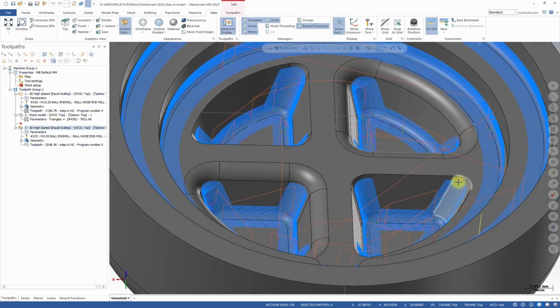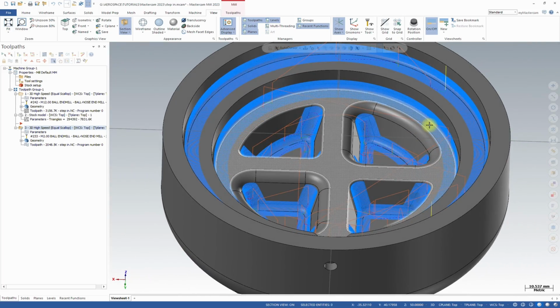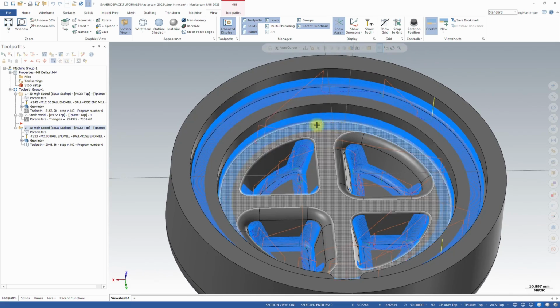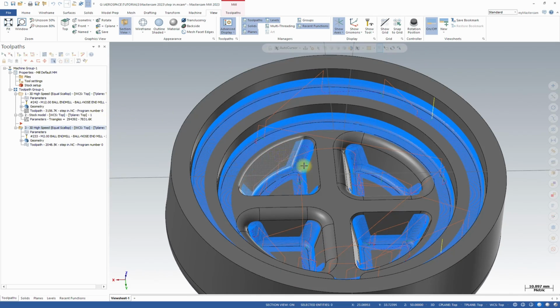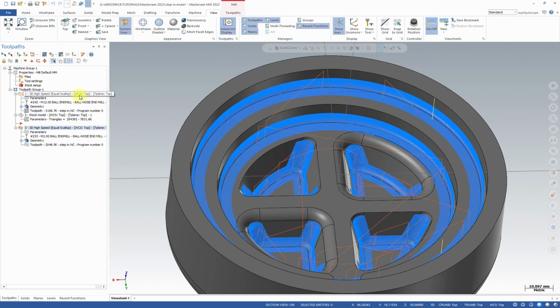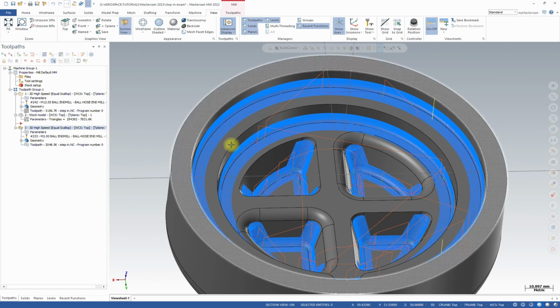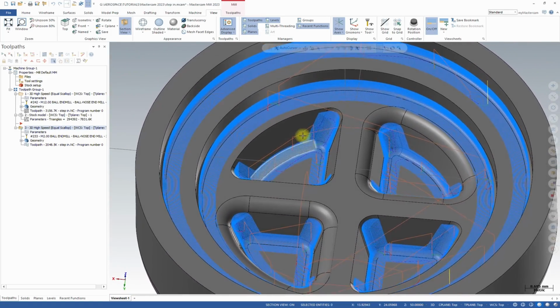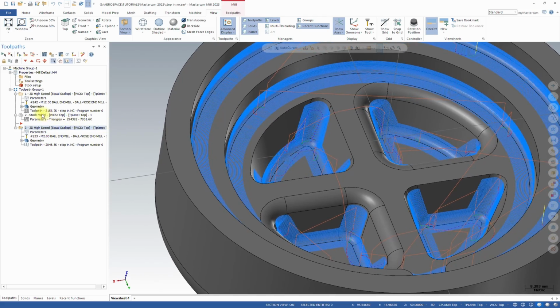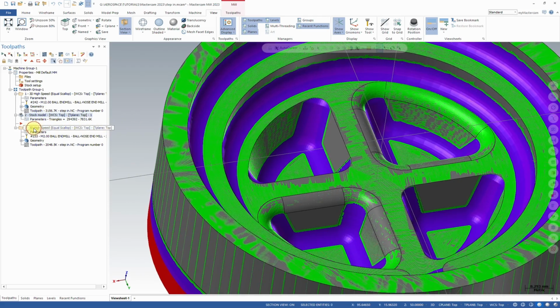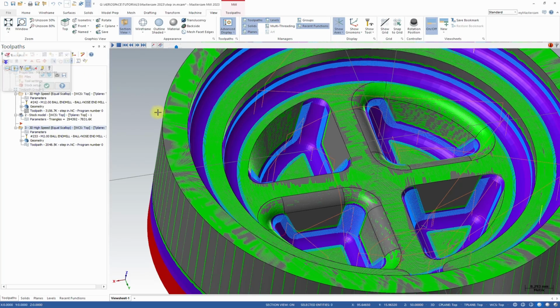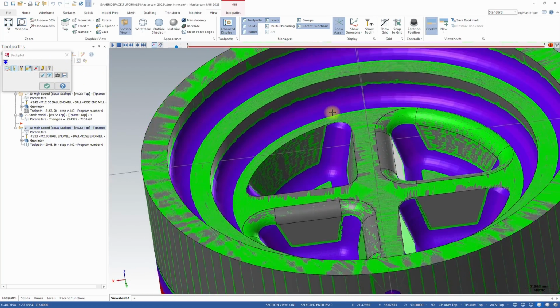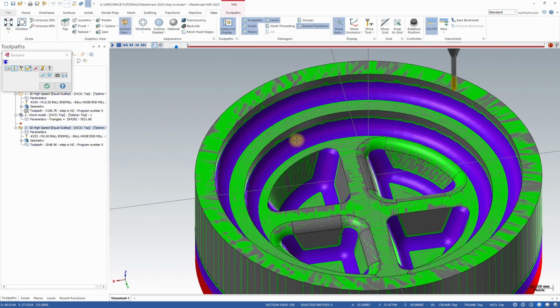Awesome. Okay, so let's now investigate this a little bit, because this is a great option. But at this moment, if we go, of course, from that big tool to 2 mil, which is no ideal situation, we will have some trouble. The tool will be buried. Let's have a look actually. Let's select those two together, and then let's run backplot. And let's take our tool first here.